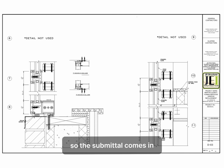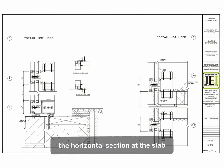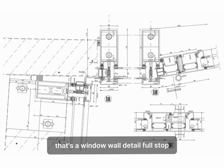So the submittal comes in. Cover sheet says curtain wall system. Product data is correct. The elevation sheets look right. The issue is buried in detail 7 on sheet SD04, the horizontal section at the slab, where the vertical mullion is sitting on a continuous shelf angle that's bolted to the face of the concrete. That's a window wall detail, full stop.